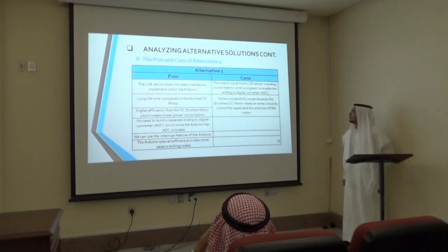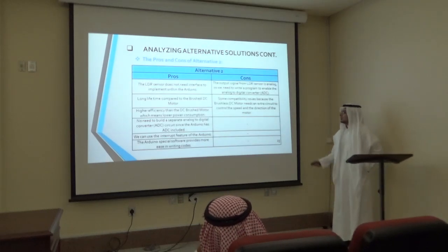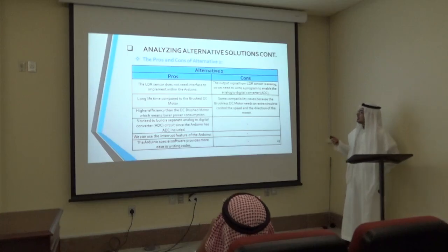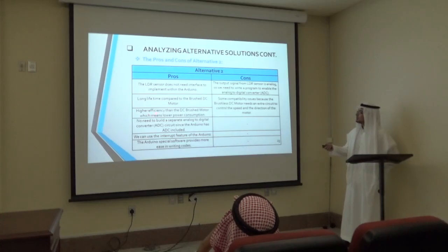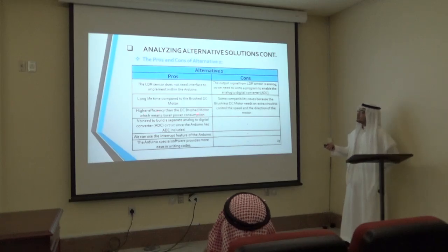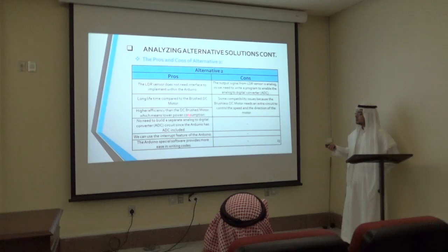As you can see, this is a table of pros and cons of the second alternative. The best thing in this alternative, the brushless DC motor has a higher efficiency than the brush motor, which means lower power consumption, which helps us to achieve one of the main goals of the project.